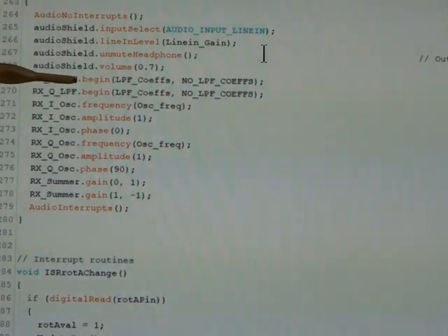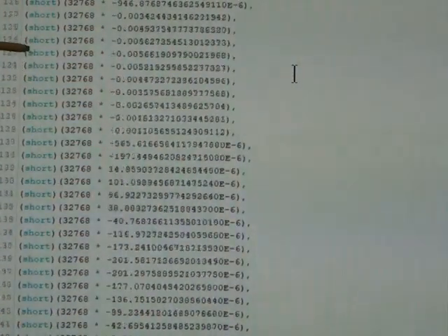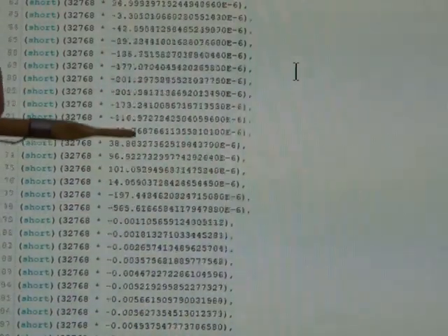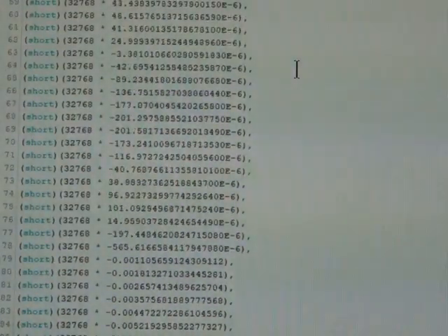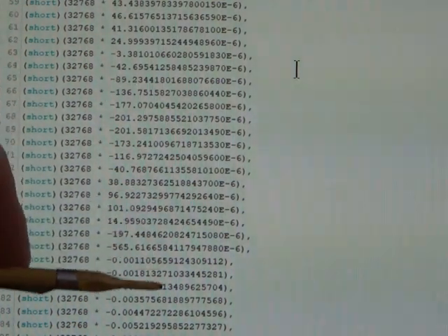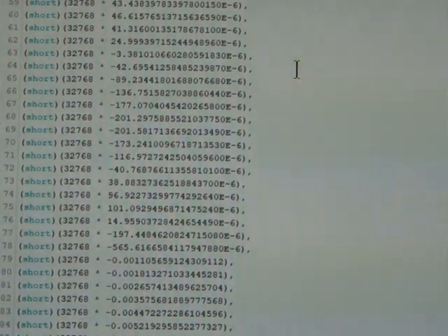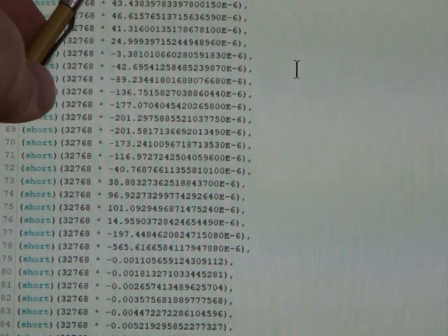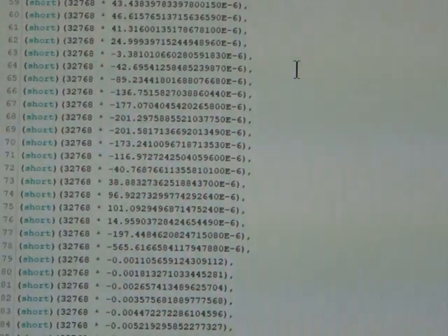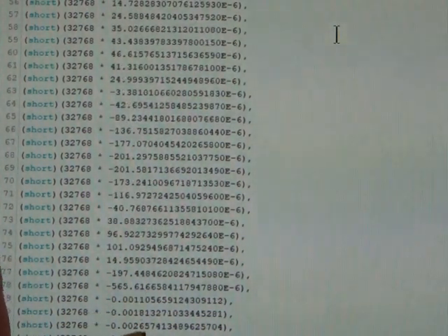I'll put this up online rather than going into details here in terms of how to turn on, or dot begin, those particular FIR filters, and also these coefficients. These coefficients here came from the Iowa Hills software, and I just ran them through a short script to append the brackets, this bit here, just to configure it correctly. I'm not entirely sure how to share that, but it's just a short script to automate the addition of that.